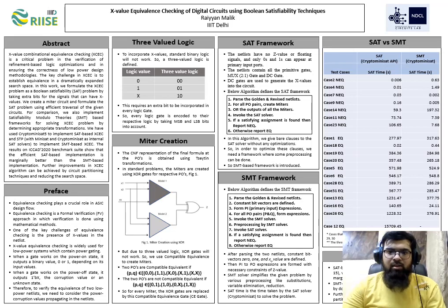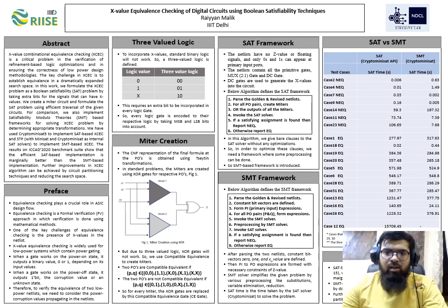Welcome everybody. This is Raiyyan Malik and I am presenting my poster on X value equivalence checking of digital circuits using Boolean Satisfiability Techniques. Equivalence checking is a formal verification approach in which the verification is done using mathematical methods and equations. One of the key challenges of verification is the presence of X values, which can be introduced due to the low power systems including the power gating.